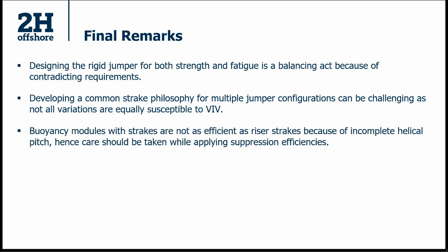If you're using buoyancy modules with strakes, please be aware that these are not as efficient as riser strakes because of the incomplete helical pitch that they have, and hence you need to ensure that you apply a lower efficiency in order to make sure that you're not under-conservative in your VIV predictions.